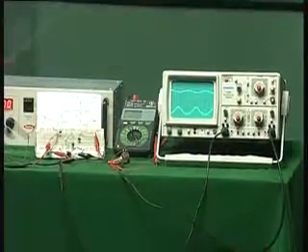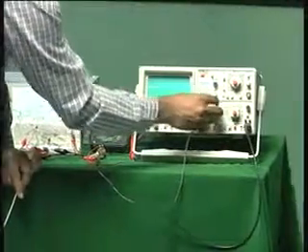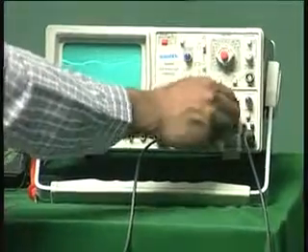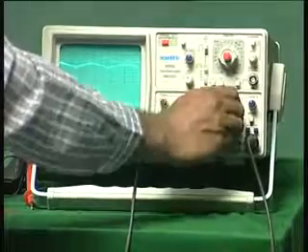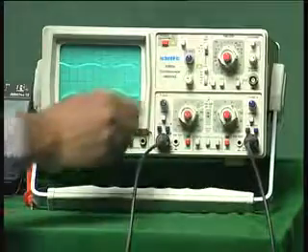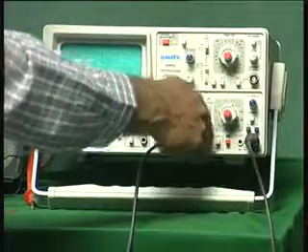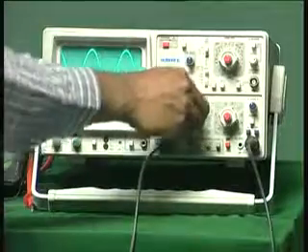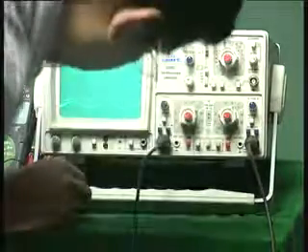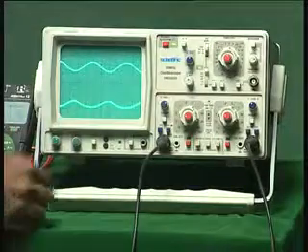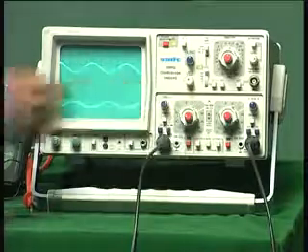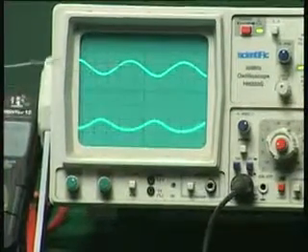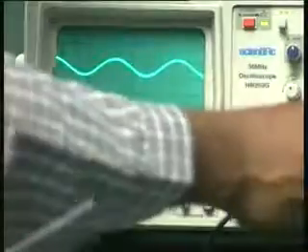How do I know it is amplification? For that you should see the amplifier settings here in the oscilloscope, which are maintained at different points. This corresponds to the highest magnification, about 5 millivolt. This is around 10 millivolt, and this is about 20 millivolt. So you can see my input signal is within one division. My input signal is at one division peak to peak. That means it is about 10 millivolts is the input signal that I am applying. The output signal is the amplified version.